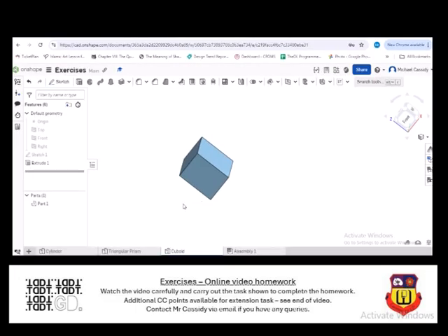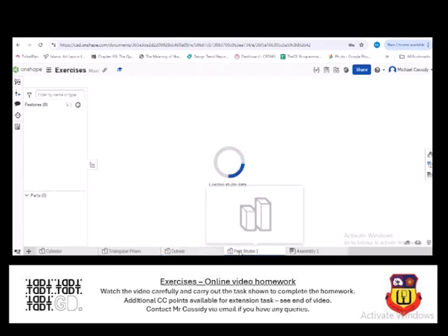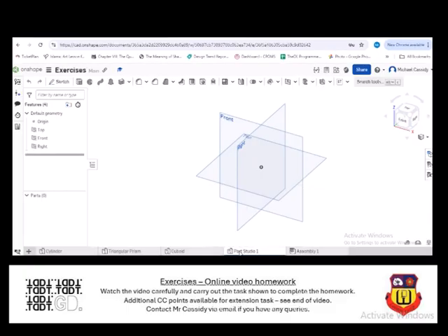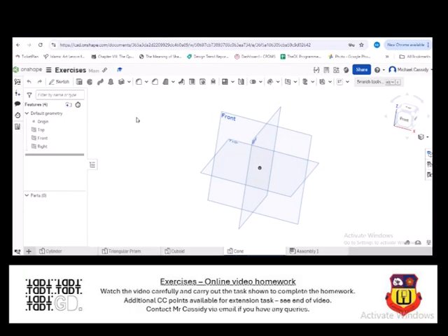Now we've got 2 more 3D forms to make, so I'm going to create a new part studio for our 4th one. This one is going to be a cone, so I'm going to rename it and type the word cone. Now where we made these first 3 using the extrude tool, for this one we are going to use the revolve tool. That's one of the other main ways in OnShape that we can make things 3D. So let me show you how to do it.